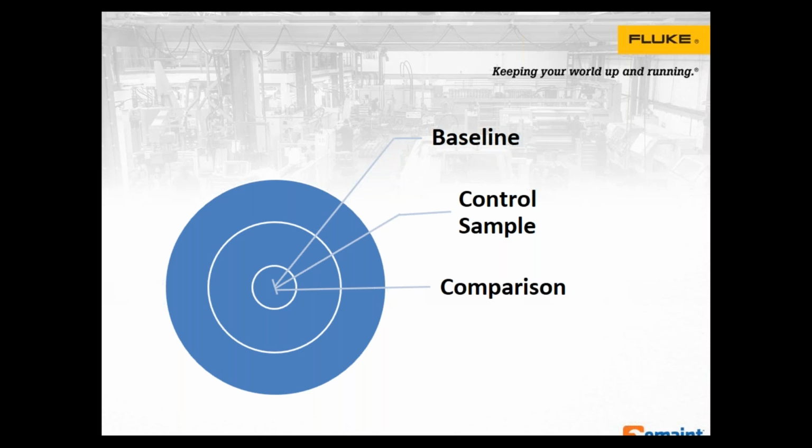So I was very, very careful, and I would take standards with me, NIST traceable calibration standards. That could be a dead weight. In some cases, it might be a control sample. But the idea is, how do you check it? How do you know for sure that the output's reading right? So if you have a way to introduce a calibration or to verify the calibration, that's the easiest way to do that. But the key on the baseline is understanding all the variables that go into having a true control sample and a true comparison.